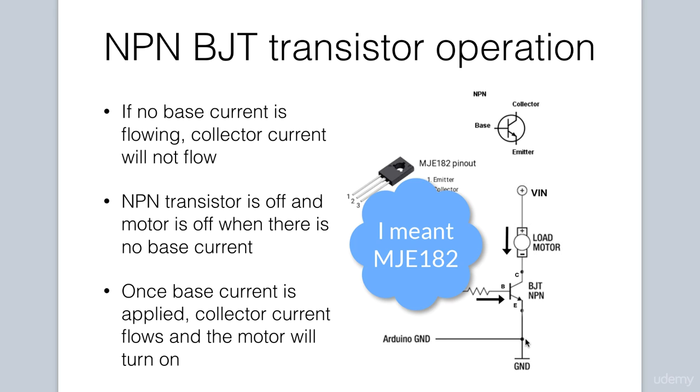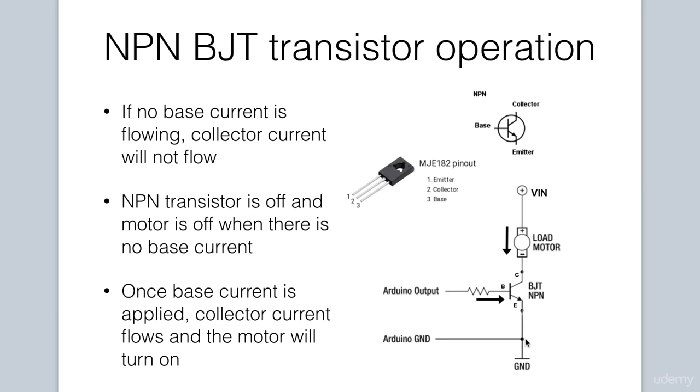We are using the MJE182 NPN power transistor as it can handle higher currents and voltages passing through it. We are actually incorporating pulse width modulation as well to also control the speed of the fan. The longer the on duty cycle that is applied, the faster the fan spins. We will see this in more detail later on when we examine the code.